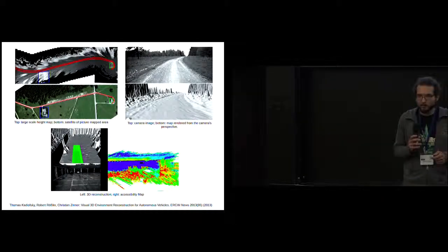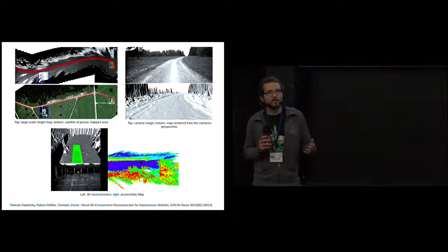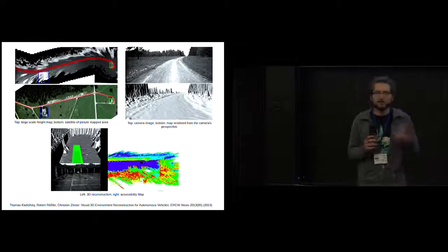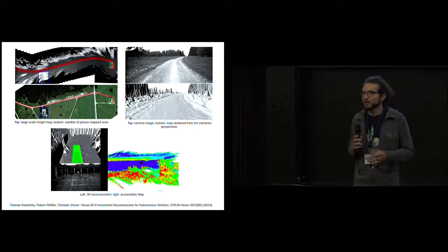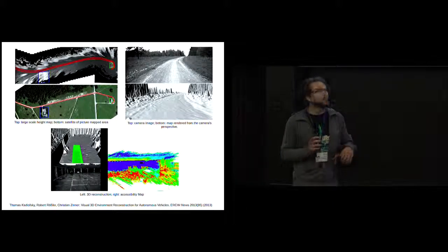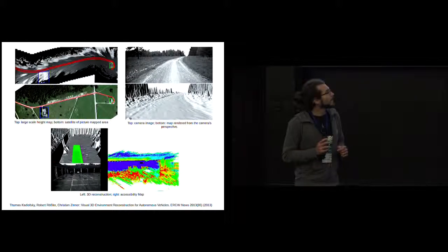We developed a mapping system where we do the sensor fusion, so it's unimportant which kind of sensors you use. Basically, we have a stereo camera system and a laser system, and fused all the data into a 3.5D representation of the environment of the robot.